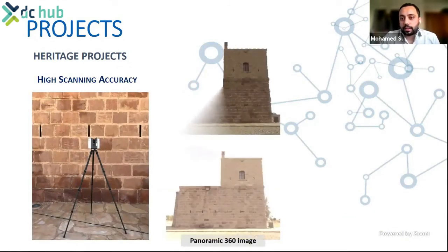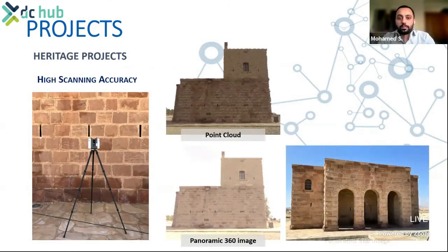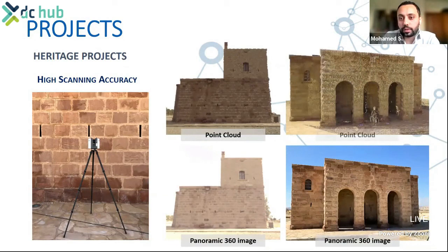Laser scanning of the existing condition can feed the BIM model with the most crucial information before starting assessment and/or restoration. And I have to mention that in heritage projects, we have to scan in high resolution, which takes more time.